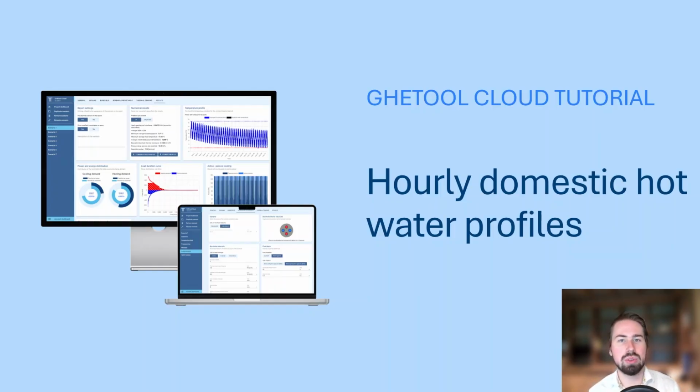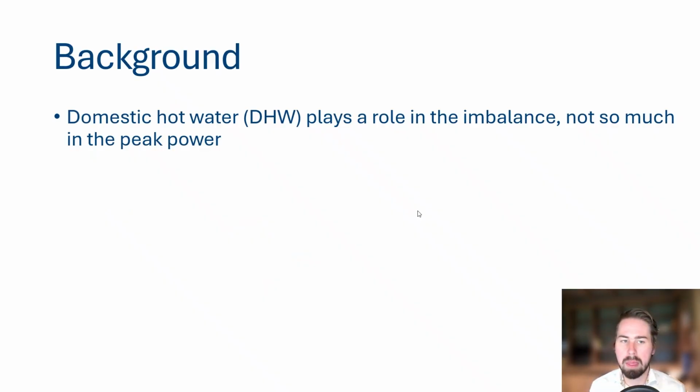But today I want to talk to you about a new feature, a small addition with perhaps a big impact for your project, and it's about hourly domestic hot water profiles. Now, to recall, domestic hot water, or DHW, plays an important role in the imbalance of your borefield. For example, in residential projects, we know that our domestic hot water demand can be in the same order of magnitude as the heating demand when you have a well insulated building.